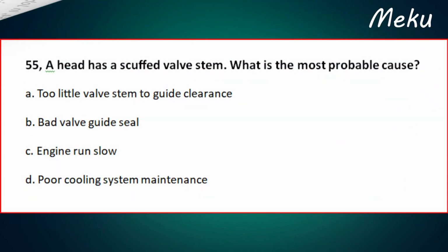55. A head has a scuffed valve stem. What is the most probable cause? A. Too little valve stem to guide clearance. B. Bad valve guide seal. C. Engine run slow. D. Poor cooling system maintenance.